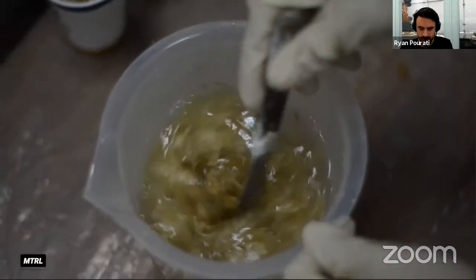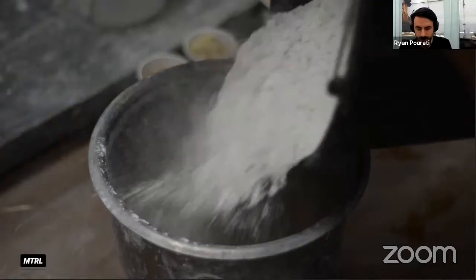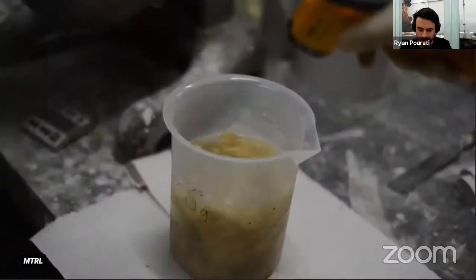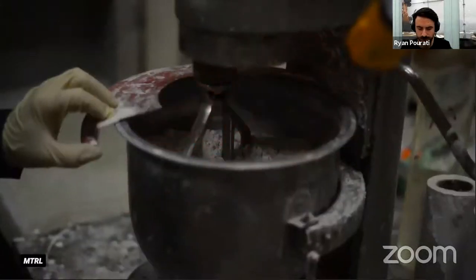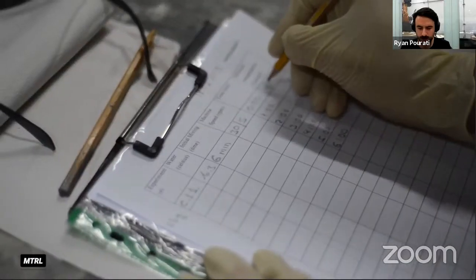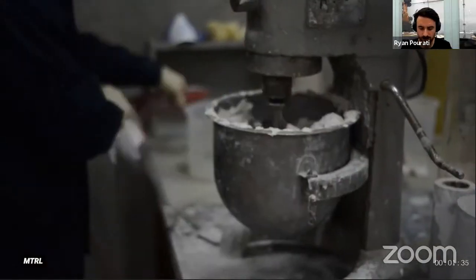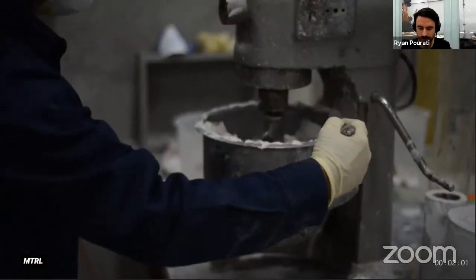Rotational casting is an existing method that produces hollow elements with complex geometries made out of polymers, mainly liquid polymers. This method utilizes biaxial rotation to generate centrifugal forces and disperse the material in the mold until it hardens. Rotational casting is highly efficient for producing lightweight plastic objects.